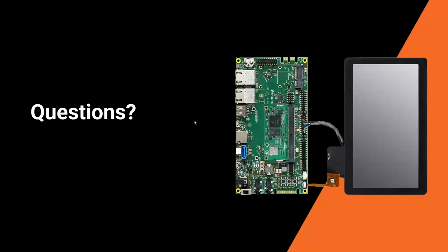We have another question about how to initialize the display. Basically, for each specific backend that you're going to use, either SDL2 or framebuffer or DRM, because there's also the DRM, but we haven't seen very nice performance with the DRM backend, the documentation provides a specific display initialization sequence. So it's just documented in the LVGL web pages, and you can find the reference to the documentation within the presentation.